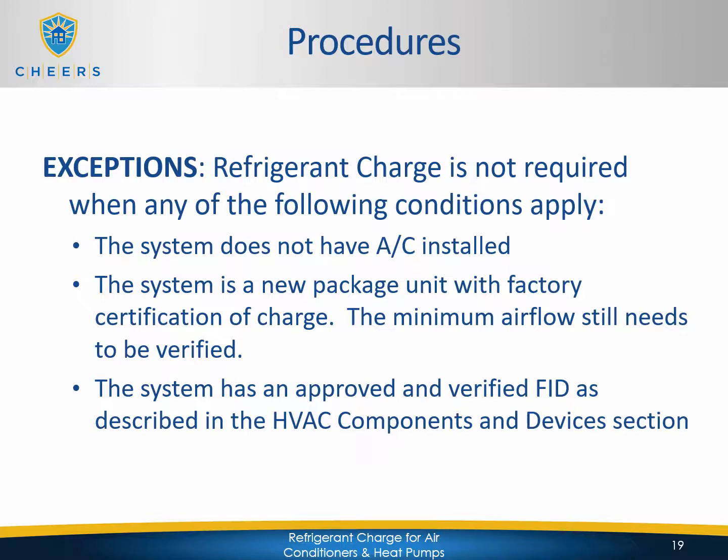And then finally, as we'll talk about in the next module, which is HVAC components and devices, there is a piece of equipment called a fault indicator display, or FID. So if the contractor has decided to install an FID, they will still have to do the refrigerant charge methods that we previously described, or that we're describing in this section. However, your verification will be slightly different, as you will only be verifying that the FID is correctly installed and is operating within the described parameters.